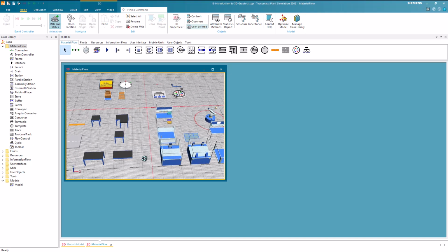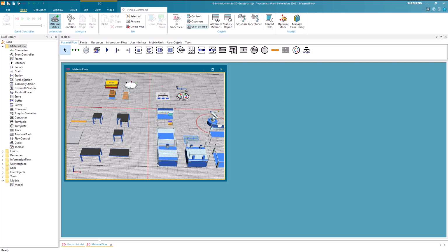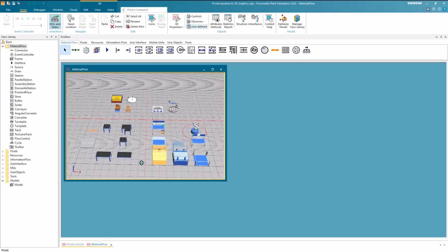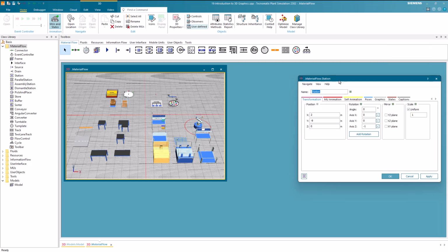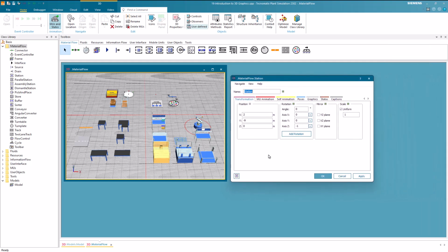Secondly, we can see that all classes of the Material Flow folder are arranged in this frame. The station is located in the lower right area. However, the coordinates of this class do not represent a meaningful position in a frame. For this reason, the inheritance of positions of a class that is arranged in a folder was switched off as a safety precaution.